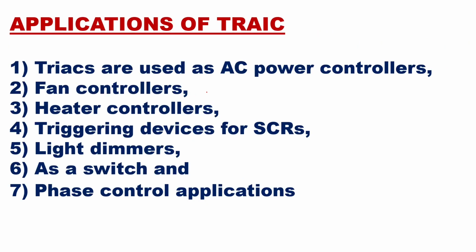Then if you go to applications of TRIAC, there are many applications, few are mentioned here. TRIACs are used as AC power controllers, fan controllers, heat controllers, triggering devices for SCRs, and light dimmers. It can be used as a switch. It can be used in phase control applications.